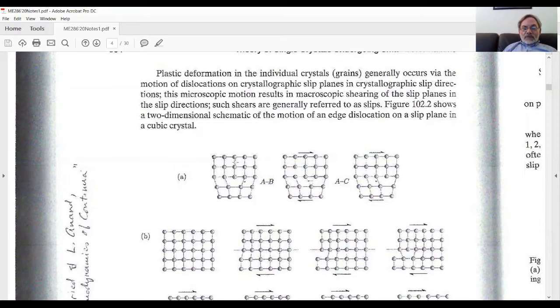And this dislocation is the basic mechanism by which plastic slip occurs, as follows. For example, imagine shearing the crystal as shown here, and let's concentrate on this line of atoms containing this terminal point of this edge dislocation. Imagine shearing the crystal, applying a shear stress or a shear deformation macroscopically. This will cause a stretching, say, of this bond labeled AB right here. This bond, if you can see it with my cursor, will become stretched to the breaking point.